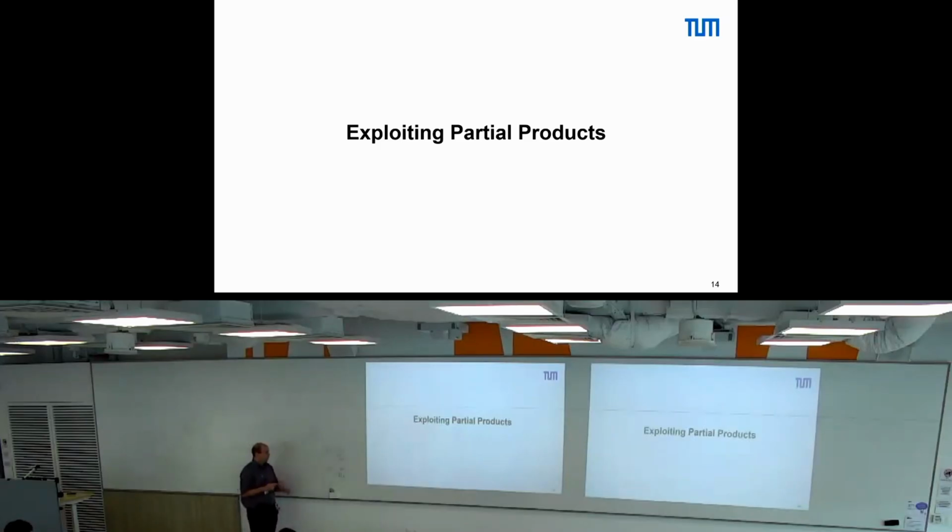Now, if you want to implement or compute the partial products, what do you need to compute, logic-wise? So adders, you need to sum it up at the end. But if you only want to compute all these individual values that are in this matrix, you can do most of the stuff with multiplexers, but what is the input of the multiplexers then? So let's say we have this number, 101 times 101, and we only consider the first line. What is the logic operation we need if I multiply this value with 1 and want the output 101? So OR, AND, NOR, NAND, XOR. It's an AND, right? So effectively, we have an AND gate between this and this gate, gives that bit.